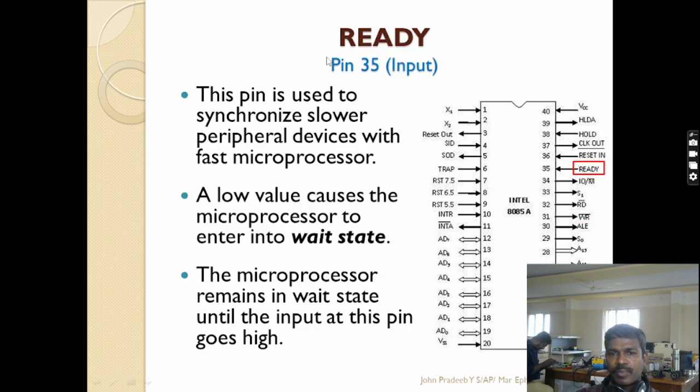The next is the ready pin. It synchronizes a slower device with the faster microprocessor. If we are interfacing any slow devices with the 8085, this signal is used to synchronize both interfacing devices.